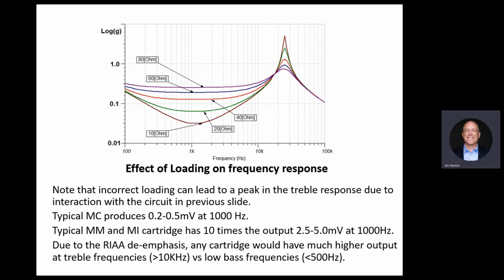And that is the mid-band gain. Remember, the bass is 10 times higher. So we're talking about an amplifier, the phono stage, that can amplify the nominal mid-band at 1,000x and the bass 10,000 times. Okay, now those numbers sound big. However, transistors and tubes are very good at amplification. They can amplify a lot. So some manufacturers prefer to break the gain into smaller portions, so each stage has less gain and they have more stages. For other reasons too.